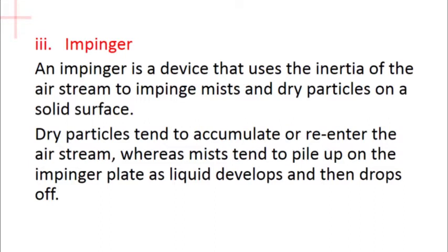Dry particles tend to accumulate and to re-enter the airstream, whereas mists tend to pile up on the impinger plate as liquid develops and then drops off. To increase the effectiveness of collecting, liquid sprays are also employed to clean the impinger surface.